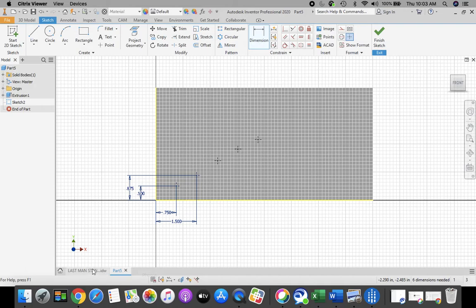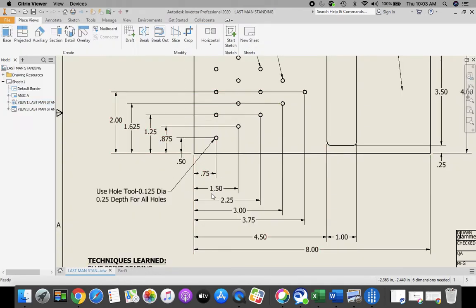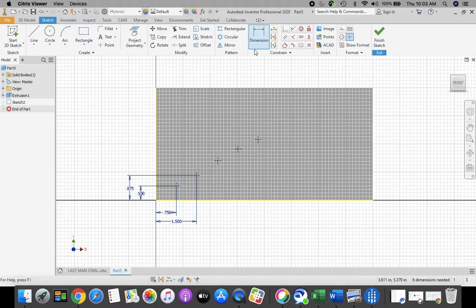Continuing with my dimensions, you guys can go back and reference this sheet, but I'm going to continue dimensioning to get these 5 points dimensioned at an angle. You can follow along. Dimension from the bottom of my part to the third point, bring this dimension out to the side. This dimension is 1.25, green check mark. Dimension from the left hand side of your part to that third point, bring this dimension down. This dimension is 2.25, green check mark or enter on your keyboard.